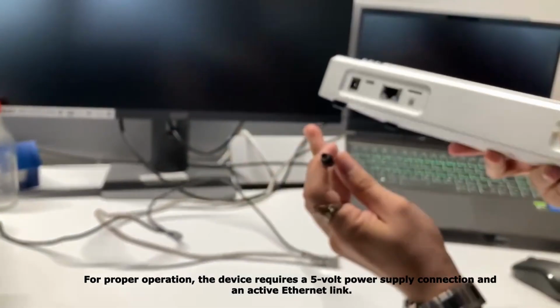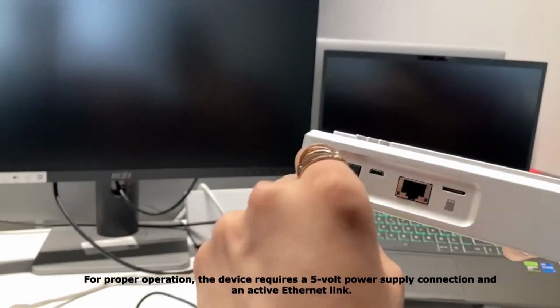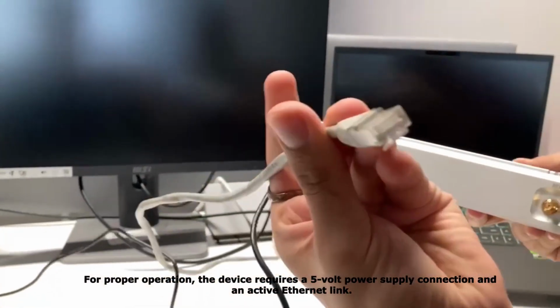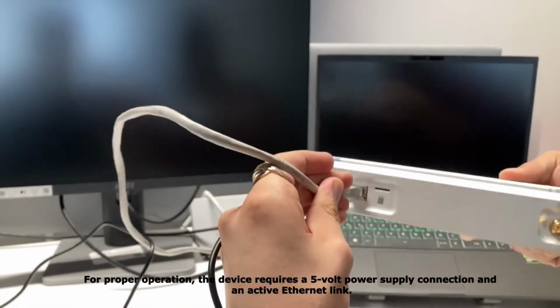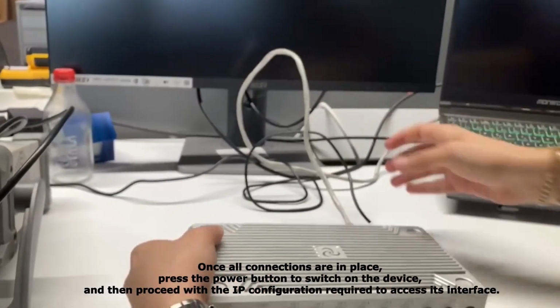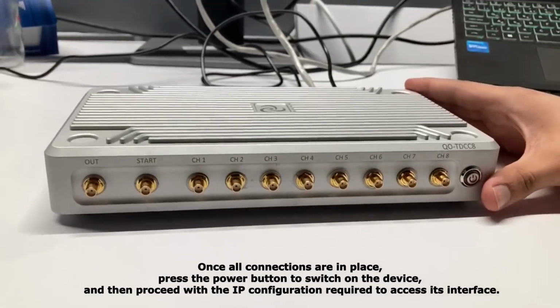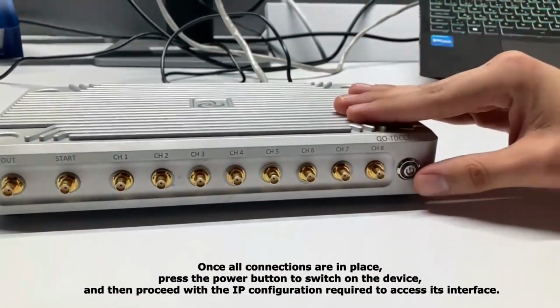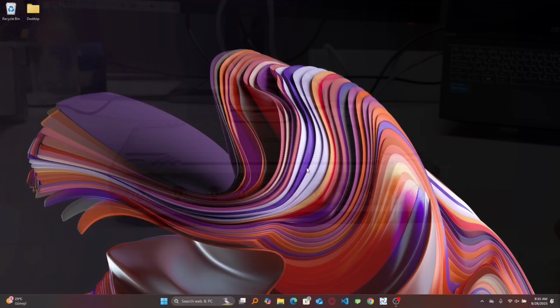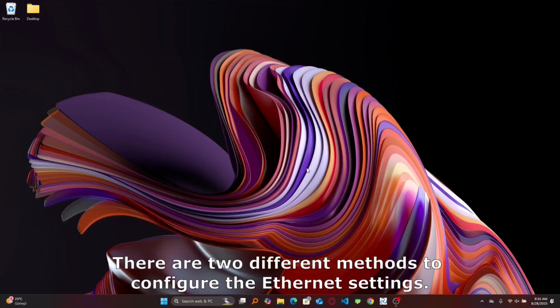For proper operation, the device requires a 5-volt power supply connection and an active Ethernet link. Once all connections are in place, press the power button to switch on the device, and then proceed with the IP configuration required to access its interface. There are 2 different methods to configure the Ethernet settings.